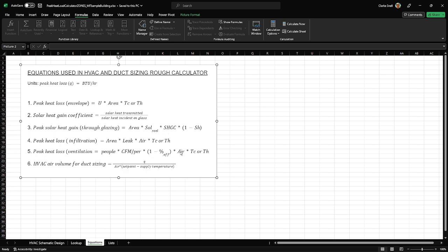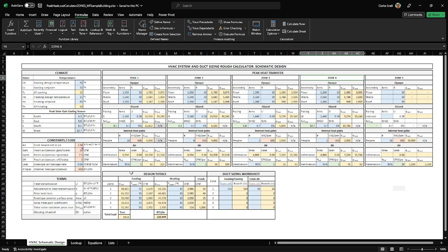Skip this for a second. Times that air constant times delta T. This is simply the efficiency of the ERV. So if I have a 95% efficient ERV, then that's going to be a very small number. It's going to multiply times this CFM and make it much smaller, right? So we're not going to lose very much heat. So that's what happened here. If I make this 0, I've got 1,200 and 2,500 BTUs per hour in heating and cooling load. But if I make it 95%, which is totally doable, I can really drop that down.